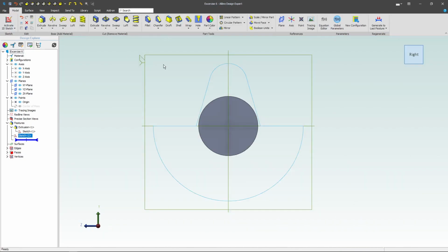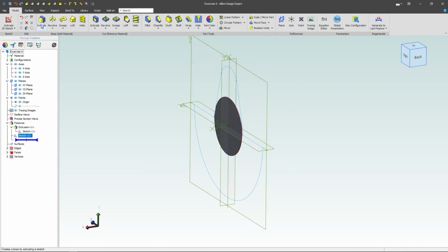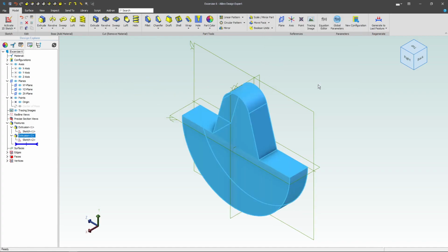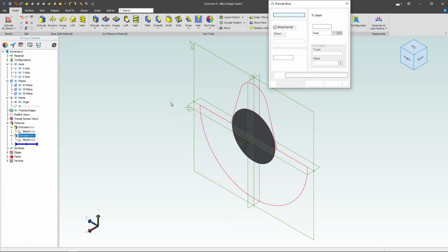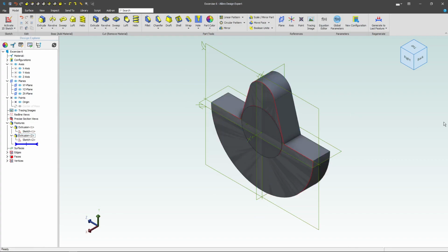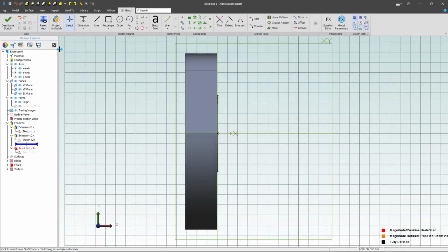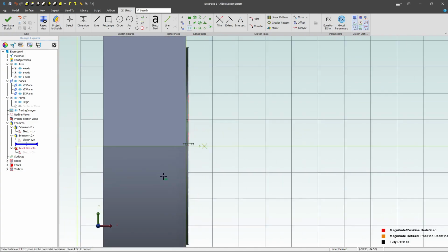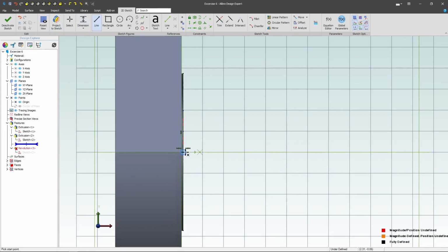Next, we'll deactivate our sketch, and I will give an extrusion of 40. And actually, let's go in the opposite direction. So we'll just click reverse right there. Next, I'll sketch on my YX plane. All right, from here, I'll start with my line. I'm going to insert a vertical line, and we'll go with a coincidence from here to this point, so it's sitting right on the edge. We'll grab a horizontal to the origin, and then I can start to sketch my part out here.